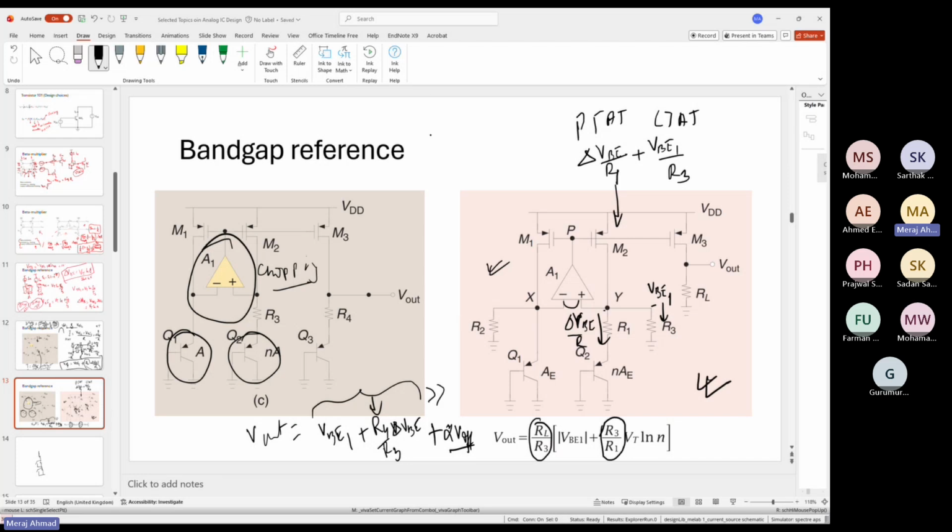For example, if you have multiple blocks in your signal chain and you want to optimize the noise, the lowest noise decides your whole SNR of your chain. So if you start with a spec, if you give me a spec, then we can have one design example where, from the spec, we start from the simplest design and see how we go and try to meet that.